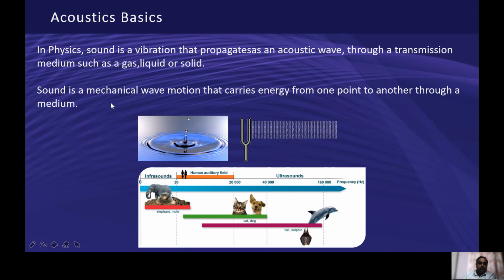Now you have to correlate the different sources of sound that can come into the picture. For example, that could be a sound coming from the engine room, or from the road and tire. Some sound coming from the structure is called structure borne noise, and that's how you differentiate between structure borne noises and airborne noises. Structure borne means the mechanical sounds which come or accelerate once the vehicle is in motion, and airborne noises are the ones that are an effect of specific mechanical systems.